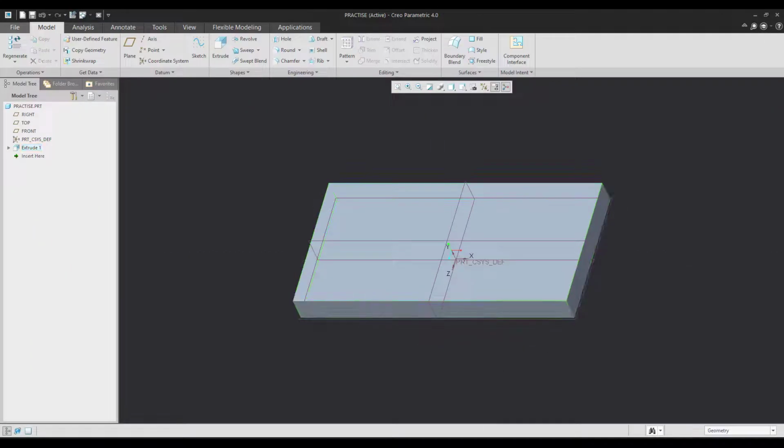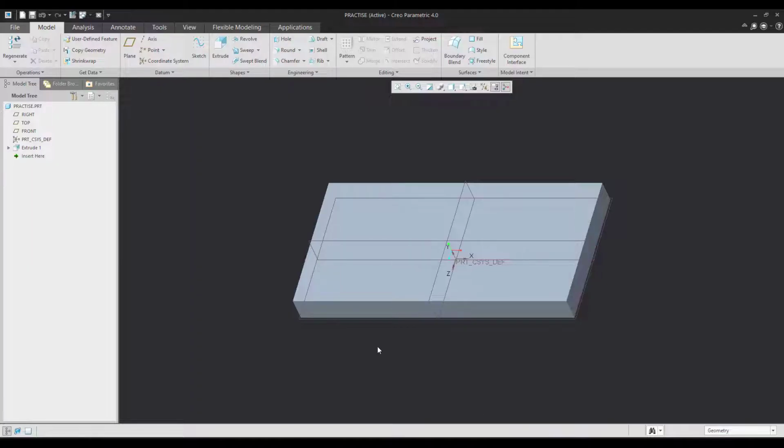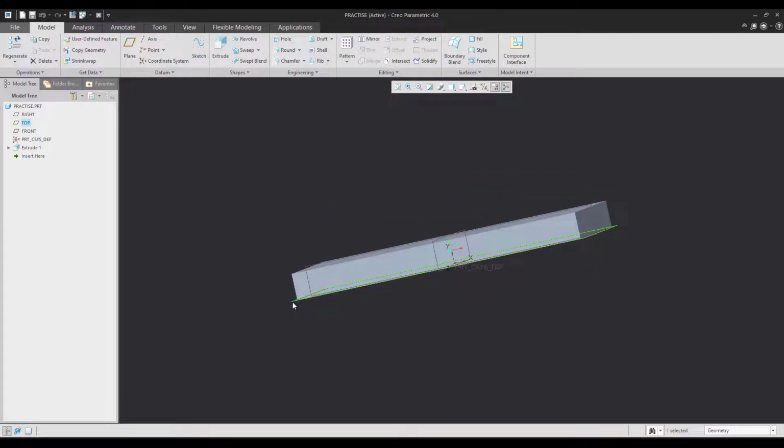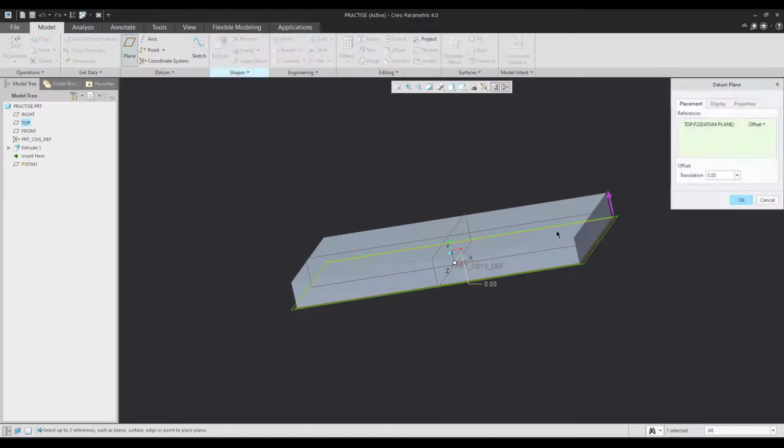Yes. Now there's a circle as well. The height of the circle is 100 from the base. So I can directly take a plane. The reason why I'm taking a plane is because I want to maintain the 100 from the base and not subtract 100 minus 16 and add material from here. So I'd like to take the 100 dimension first.